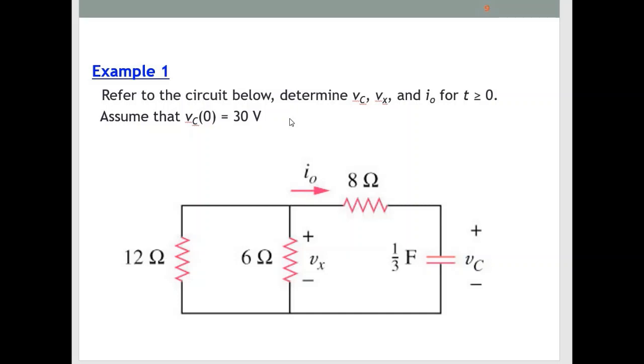Okay, now try to change the circuit into the basic figure of RC. If you can draw like this one, this is R and this is C. Maybe we can try 12 parallel with 6 and plus 8. We will get the R equivalent, and we can use this formula V0 e^(-t/RC) in order to get the VR and also VC here.